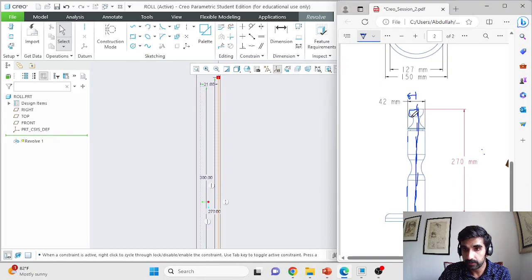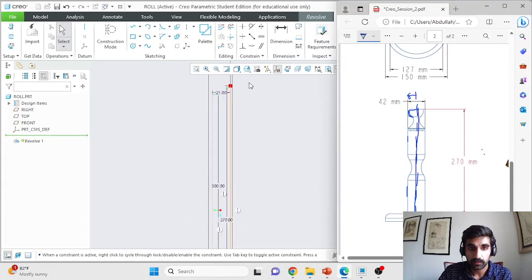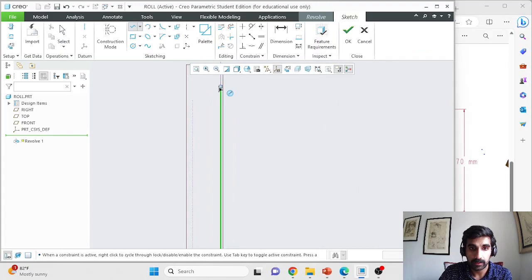Now I'll try making this top semi-spherical feature. For that, I'll start with a line. You can bring it all the way out over here, and this snapping is telling you right away that it's 21 mm, and that's one of the benefits of having made a projection line. If you look at the cross section, you see that it's actually slightly less than 21 mm. So I'll select a point over here. I'll press escape or the center mouse button to stop making further line segments, and